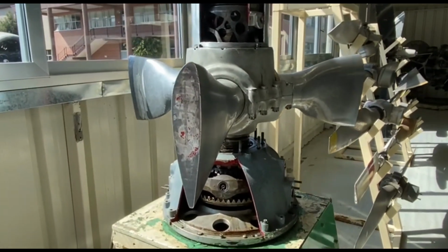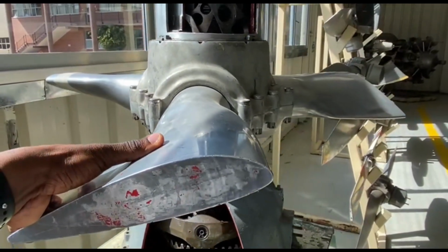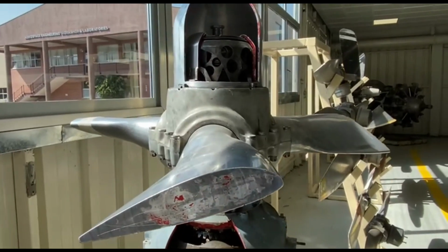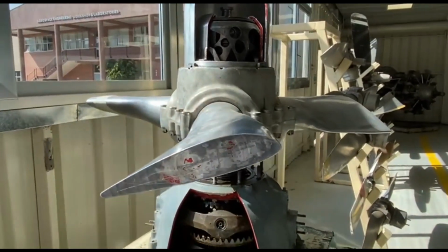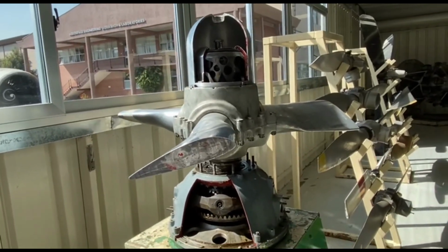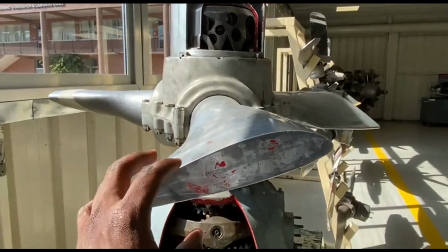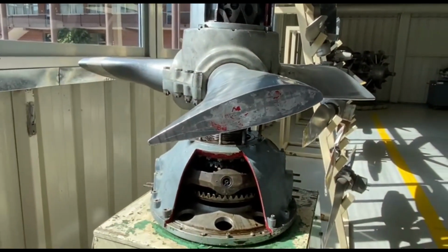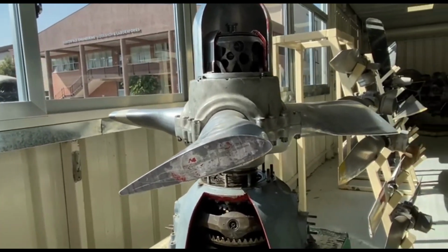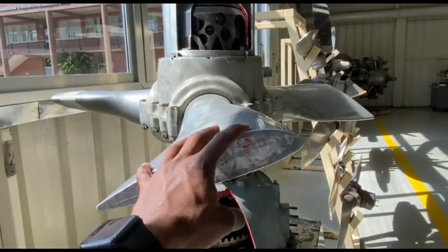The position that generates the lift is this one. In this position the blade can cut the air and generate lift. If you look at one blade of a propeller, the airfoil shape is there, the same as the wing. So yes, the blades are also generating lift on the turboprop engine.